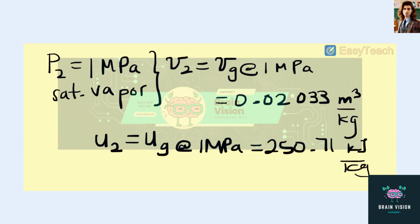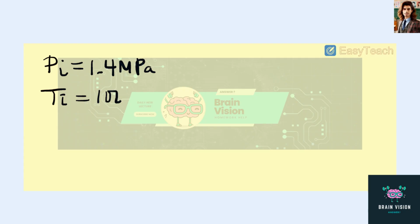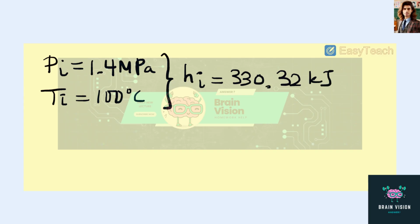Now we have to look at the refrigerant that is entering the rigid container. So we know that Pi, which we're going to use to represent the pressure of the supply line, is equal to 1.4 MPa, and Ti is equal to 100 degrees C. Using this information, we can find the entering enthalpy. Specific enthalpy is equal to 330.32 kilojoules per kilogram.